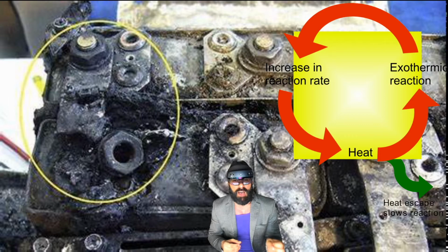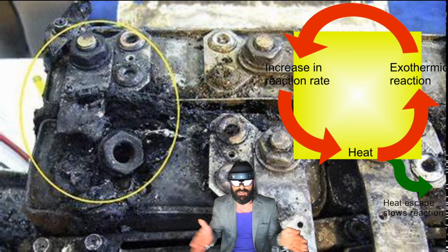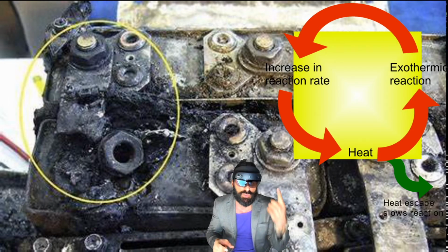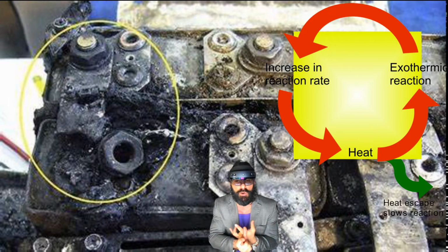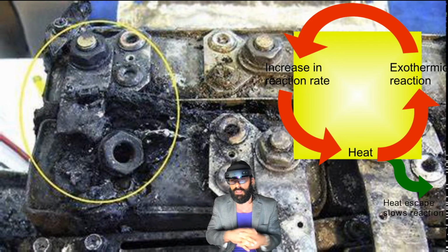Now, valve regulated lead acid batteries are 99% recyclable, and as compared on energy density and footprint, now we're going to start installing lithium batteries in data centers that are 1/5 the size, 1/5 the weight, but 3 times the energy density, and having a thermal runaway mitigating design or system, and as I say, hybrid systems, not just one, where you would have a material science component of this, triphenyl phosphate, or some kind of other material that is going to mitigate that expansion, that exothermic heat generation. You need to have that in place.